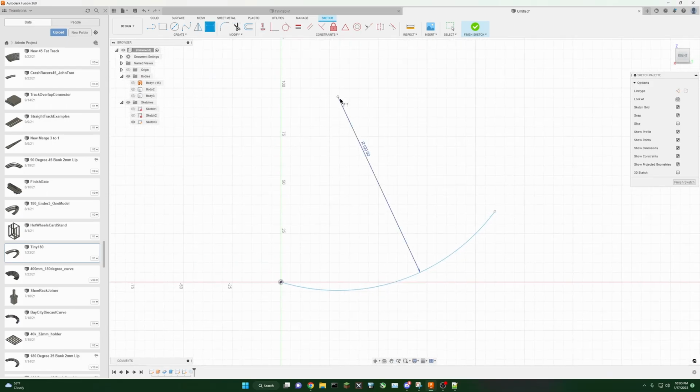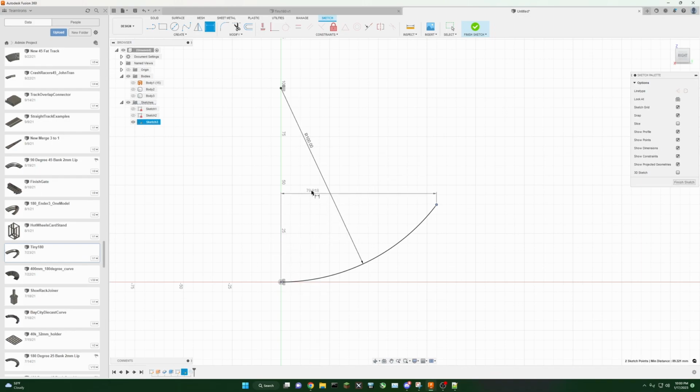It's pretty big. I'm going to pull this circle so that this is straight. So for this to come out straight, we need the center of the circle to be directly over this origin point. So I'm going to go to a horizontal vertical constraint. I'm going to say I want this to be over this. Now the only other constraint we don't have is how long this arc is. So I'm just going to click these two, and I'm going to set a distance of, let's say, 90.